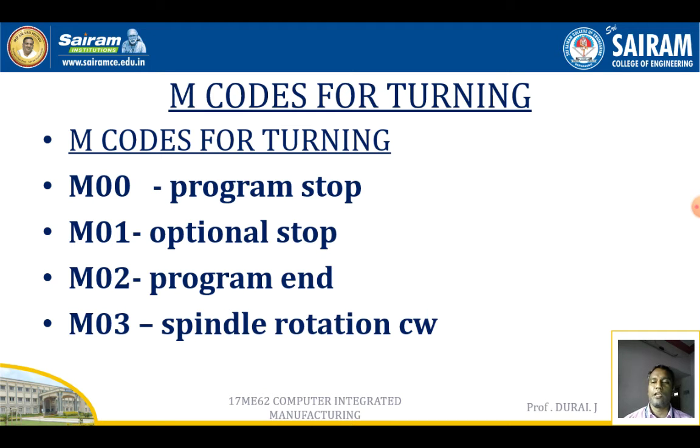So first, M00, the program stop. This is the temporary stop of the machine. For that purpose the program stop can be used. We temporarily stop the machine to remove the chips and check the machine. For that you can use the M00 code.